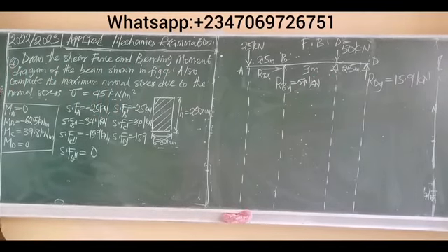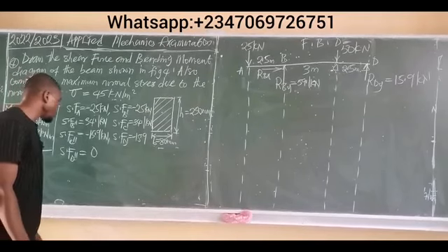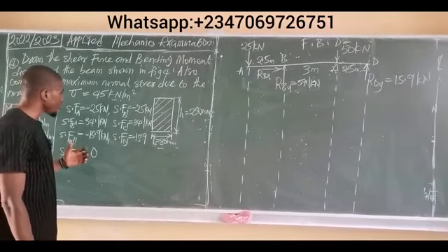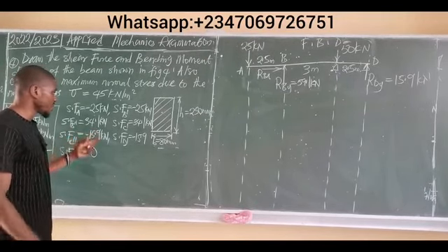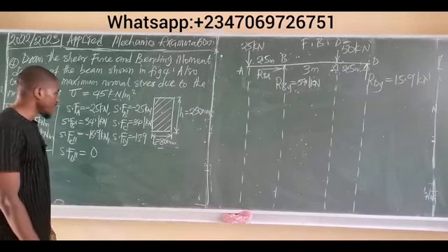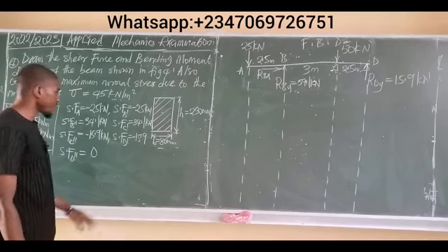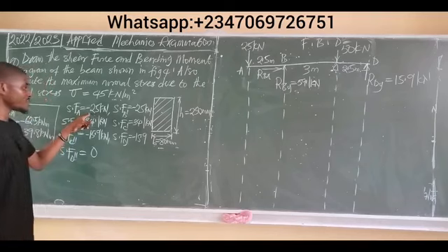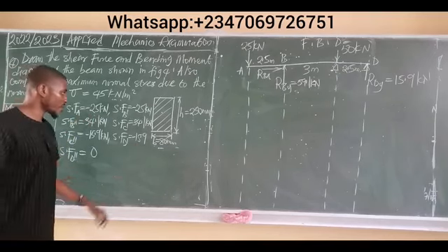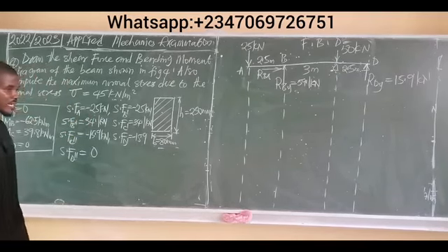Okay, so you start the numbers from the highest to the lowest. You look through the shear force values. The only positive result we have here is 34.1 kilonewtons, and that seems to be the highest. And the negative results we have are minus 15.9 and minus 25 kilonewtons. So minus 25 is the least, minus 15.9 is bigger on the negative side.